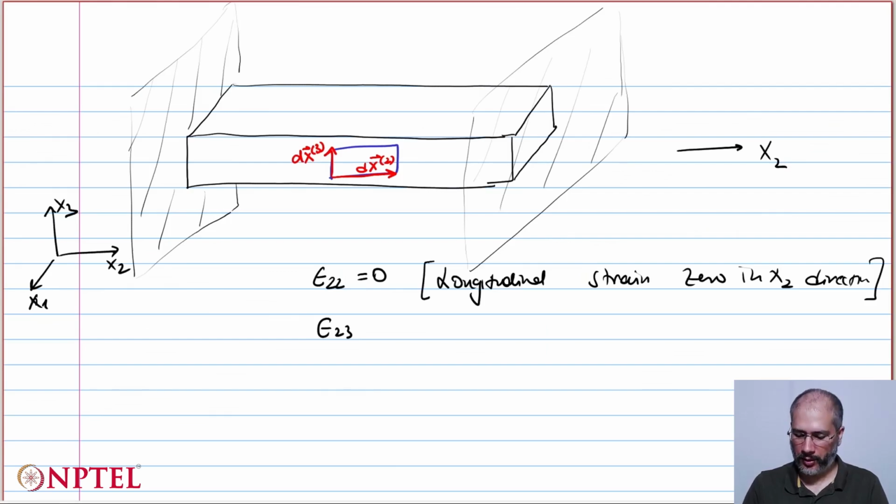And if for some reason the angle had changed, this would mean that one of the points has moved more than the other. That is the only way the angle will change, but that is not possible because of the constraint in the x2 direction. So all points move to the right or the left on this x2 x3 plane in an equal amount because of the constraint.